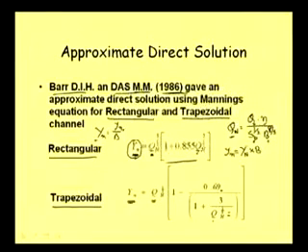For a trapezoidal channel also we can calculate the non-dimensional discharge qn first, and then we will get the non-dimensional depth. From that we will get the actual depth. In this formula there is of course always some amount of error expected, so we need to put it in the actual formula and check whether it satisfies our condition or not.